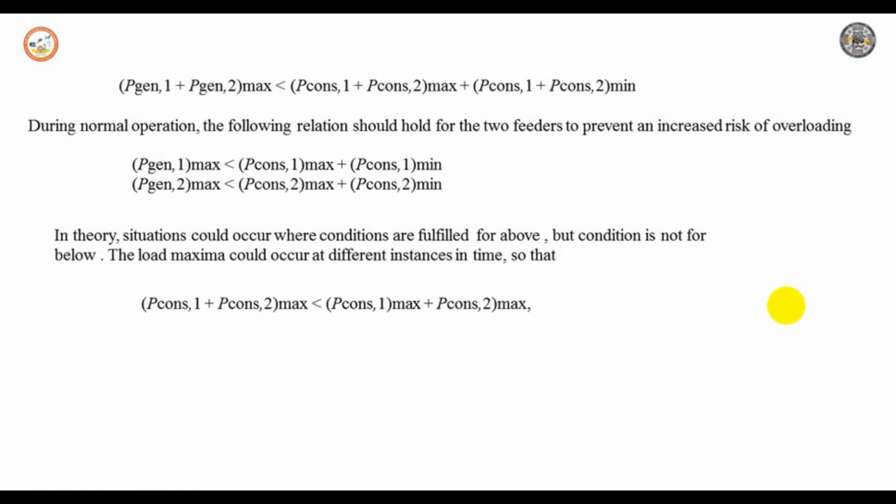it should be further noted that this gives only a first hosting capacity, beyond which the risk of overload becomes higher than in the network without distributed generation. There is also a second hosting capacity, beyond which the risk of overload is unacceptable. Extreme cases might still occur, mainly when large units are connected towards the end of the feeder. A number of solutions are available for coping with this situation.